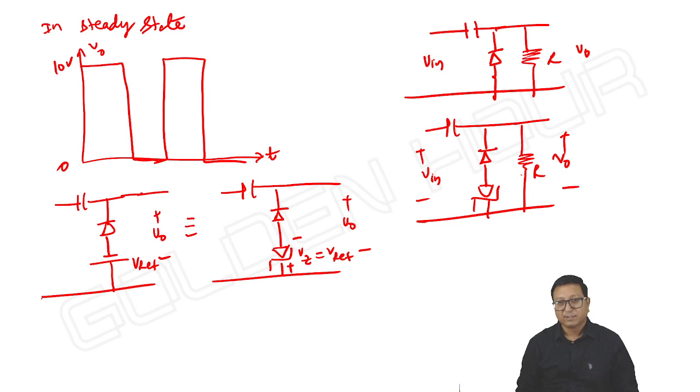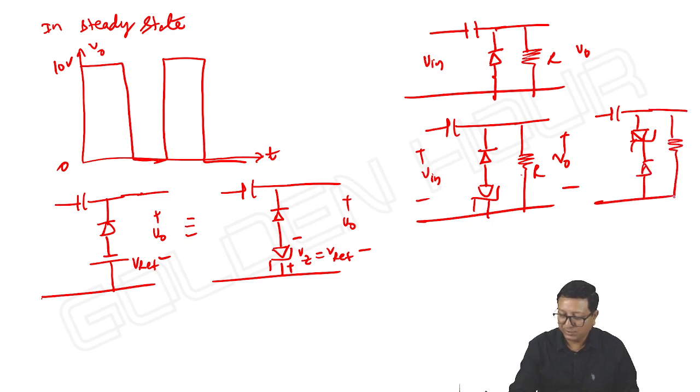Okay, with the positive clamper, the diode and the zener diode, whether it's a positive or negative clamper, both should be in opposite directions. Even to confuse us, they may show the zener diode like this and the ordinary diode upwards this way. Doesn't matter, both are in series, nothing to worry about. For the negative clamper also, the diode and zener diode should be in opposite directions. They are in series, you can take the ordinary diode first, next the zener diode, or vice versa. It is possible. That's it. So these are all the different combinations of clamper circuits.